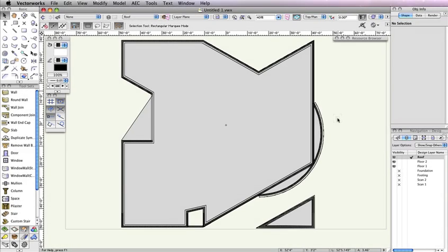Thus far, you've created the walls and roofs for this model. The next step in this project is to create slabs for the first and second floors. As usual, you'll need to set up 2 new design layers to begin, one for each slab. Since you've done this a few times now, we'll move through this process a little more quickly.